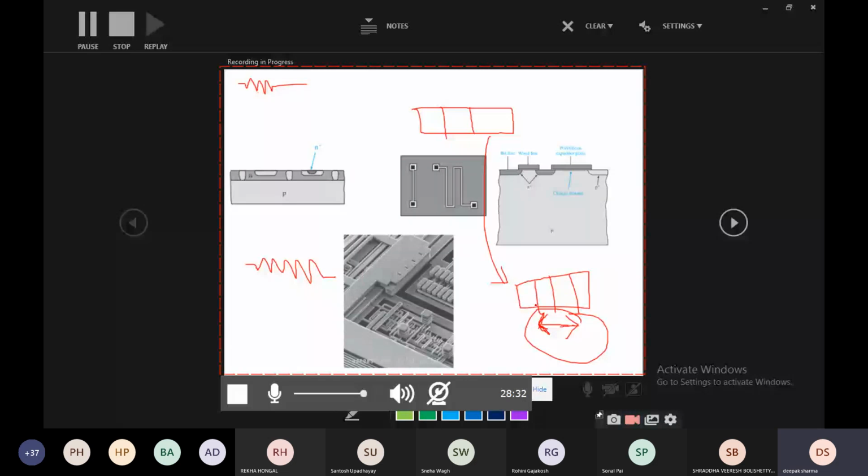If there is more reverse biasing, more width will be there, right? The depletion region will get more widened, and when there is a more widened region, then that depletion region will have more resistance. So depending on what amount of resistance we require, we can model it. Yes, we can customize it.